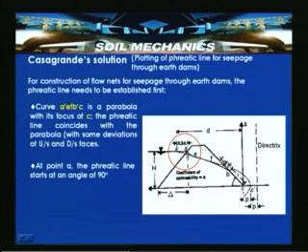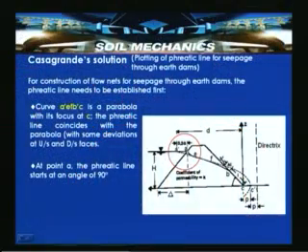So while drawing the phreatic line from the upstream face, it has to be noted that the phreatic surface has to start at a 90 degree angle with the upstream face. Here the portion of the phreatic line coincides with the parabola, and C is the focus, and C dash is at a distance P, and this is the directrix. B and B dash, this distance is delta L, and this is the small l.